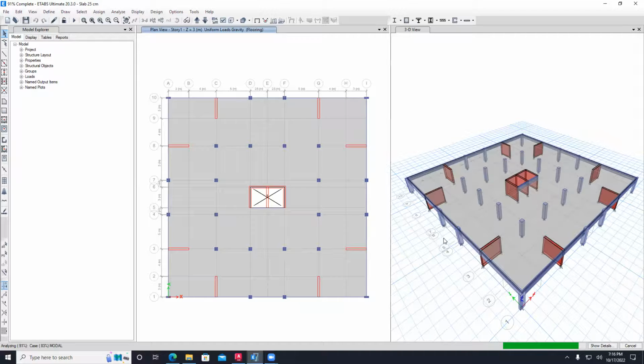If we are working with 3D models, what do ETABS and SAP do? They idealize the building. So, for example, this is your multi-story building: 1, 2, 3, 4, 5, whatever stories you have. SAP2000 idealizes each story and converts it to a mass, and puts this mass here at this elevation, and this mass here at this elevation, and this mass here at this elevation. All these masses also account for all the stiffnesses of the columns at this story.